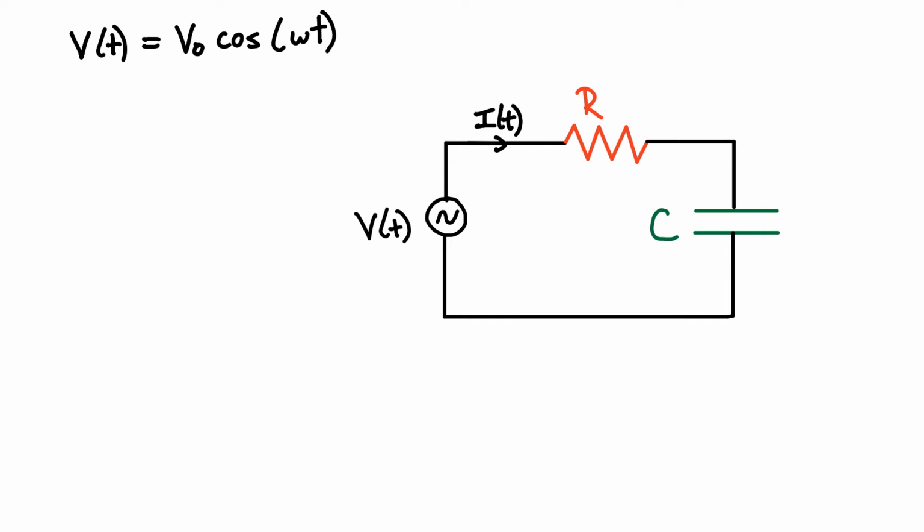All right, before I do that, I first want to apply Kirchhoff's loop rule to this circuit. So this is how the voltage varies as a function of time. I'm going to apply the loop rule starting at point A, and we're just going to go around in a clockwise fashion. Kirchhoff's voltage law simply says you add up all the potential differences across the different elements, and when you come back to where you start, it has to be equal to 0.